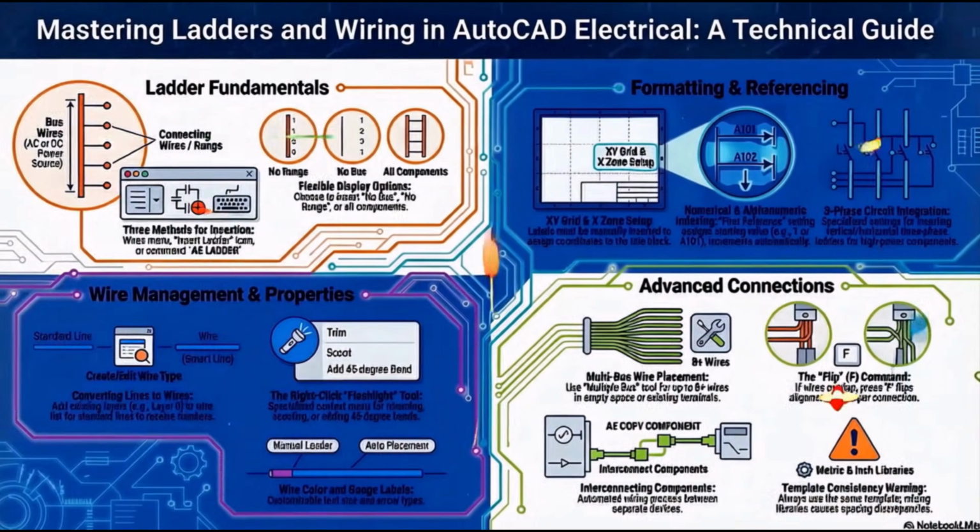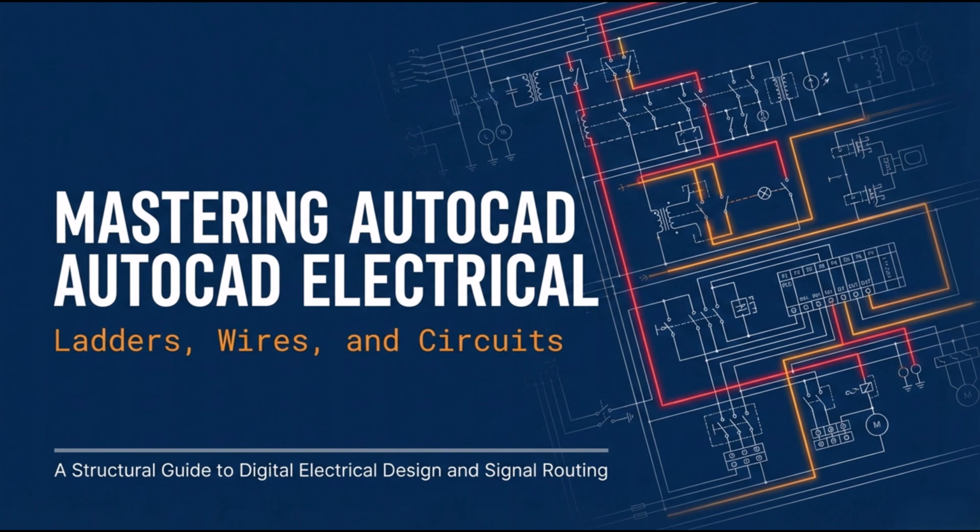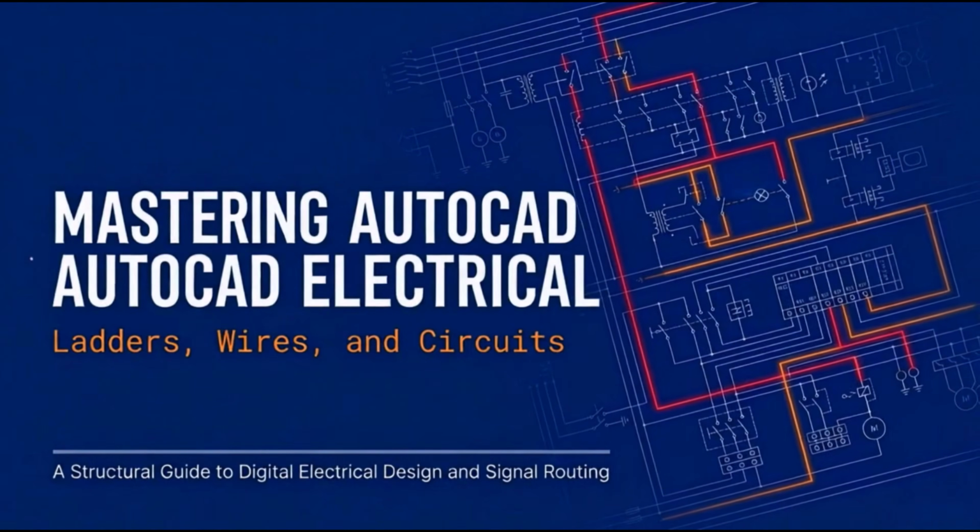But in electrical, it's a non-issue. You use the Revise Ladder tool. You just select the ladder, change the start index from 1 to A1, and hit OK. And it just fixes it. The software recalculates the entire stack instantly.